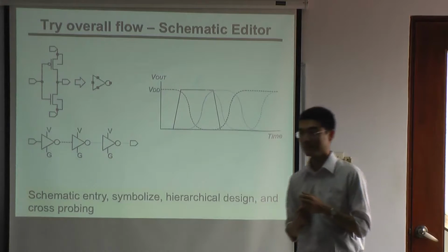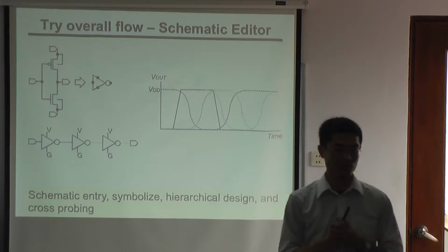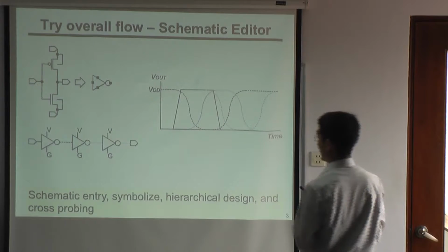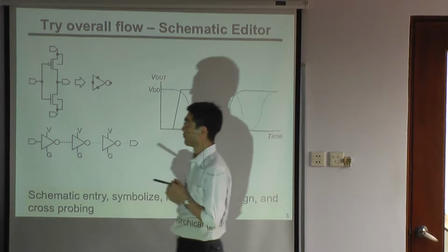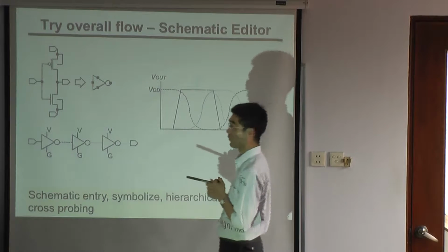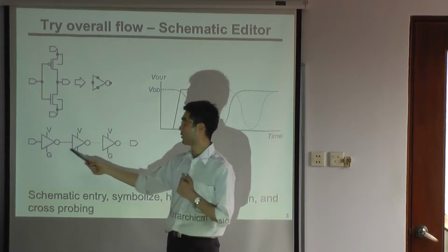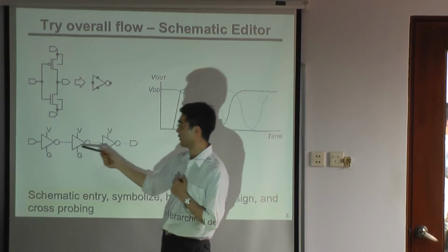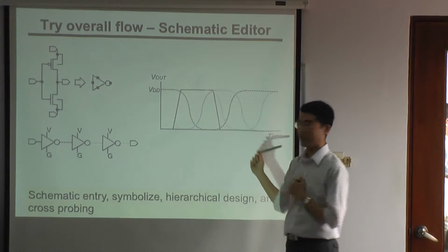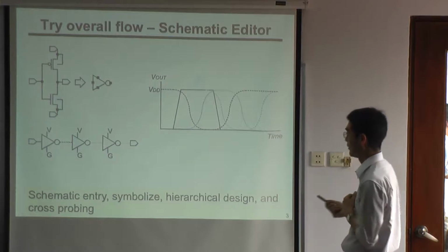And after knowing the transistor performance, first you design inverters. Of course you will do a hierarchical design: make a single inverter, connect and simulate, and see the result.